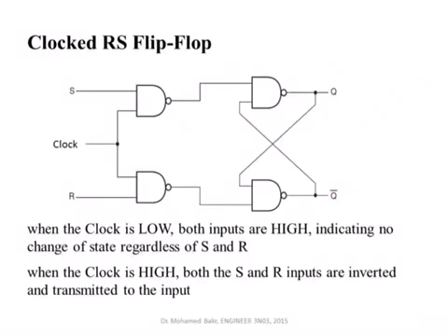Okay? So what we can do is take two NAND gates again, and then we have the clock as one of the inputs. So when the clock is low, this means that the two NANDs will create 1 and 1 here, meaning do not change. So whatever is stored in this memory element, whatever is stored in this flip-flop, will be the same. When I make the clock equal to 1, if set is equal to 1, it will be transformed to 0 at the output, meaning set the flip-flop. When you have 1 and 0, it will create 1 and 0 at the output.